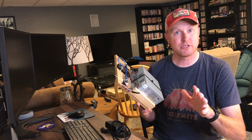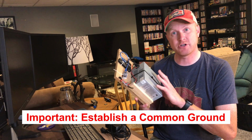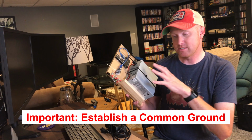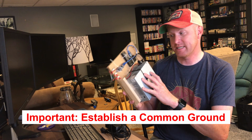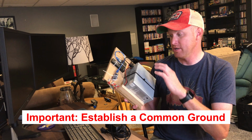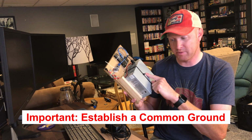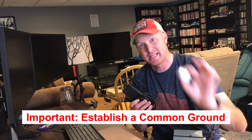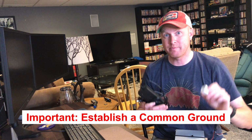Now, the next thing I want to talk to you about is setting up a common ground for your power supply and your Arduino and Raspberry Pi. Since I'm using one power supply to connect all this together, I already know that they have a common ground through the common ground of the power supply. But if I was to use a wall plug like this and say a phone charger to connect to the Raspberry Pi and control the lights, we need to set up a common ground between these two different power supplies.